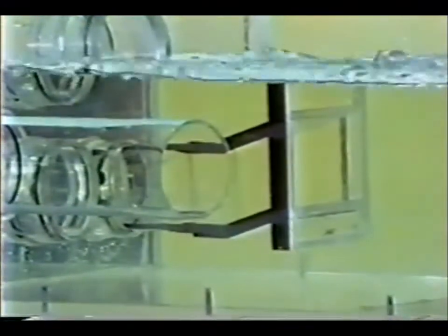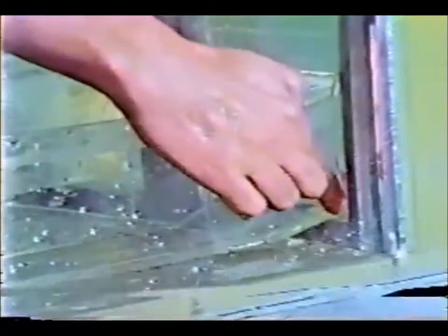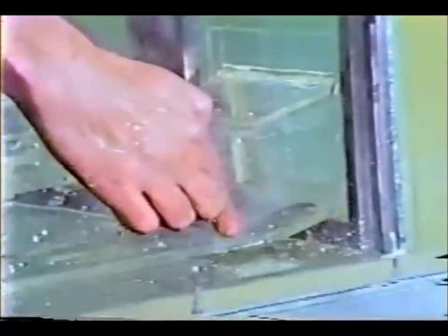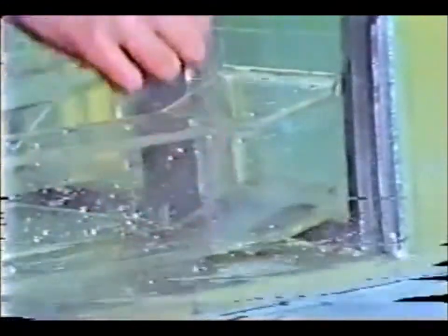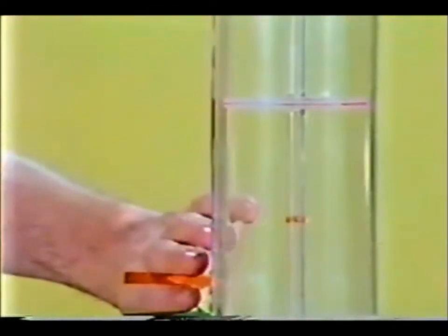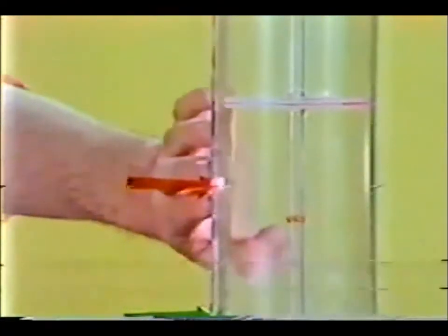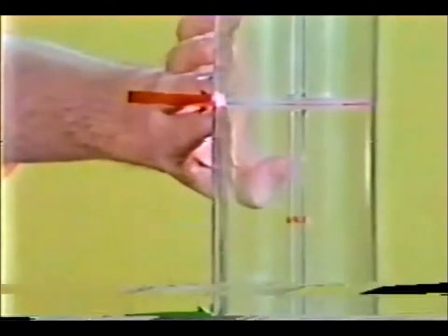So far, just circular culverts have been demonstrated, but the same amount of improvement can be shown for box culverts with improved inlets. To demonstrate this, we'll compare two inlets. One is a box culvert with square edges at the inlet. The other is a slope-tapered inlet similar to those shown previously. This inlet has 1 inch of fall in the sloping section of the entrance. Let's mark the headwater level for the square edge inlet and switch to the slope-tapered inlet.